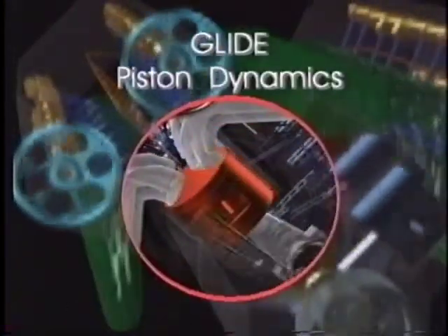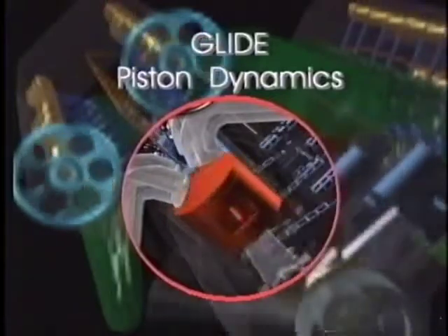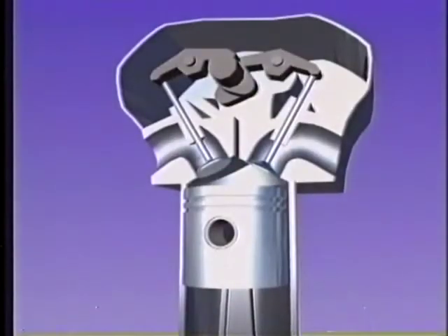Another point of interest in the engine is the piston and piston ring group, simulated with the software package GLIDE for piston dynamics. The results of this simulation are used for acoustics calculations through analysis of piston slap or for the estimation of lubricating oil consumption.